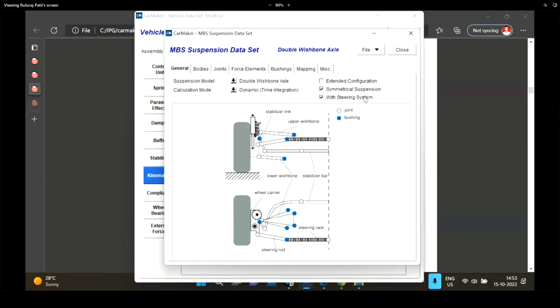So you should also look at the vehicle models which are manufactured and compare those parameters while inputting into this. If you have a symmetrical suspension and you are selecting it here, well and good, there are no issues. But if you don't, and you are basing the model just on the CAD inputs, the CAD model,